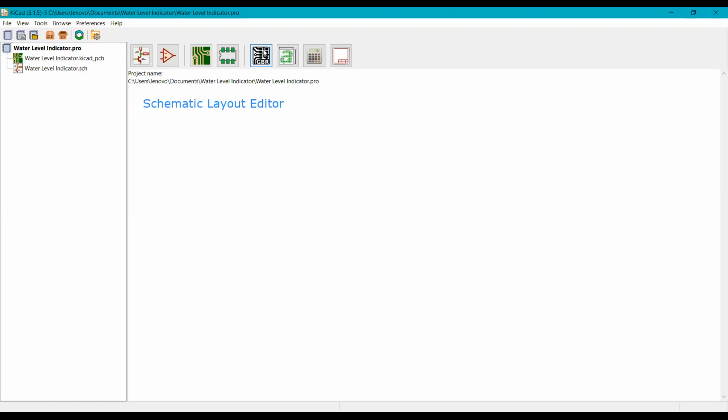Then you will have to generate your Gerber file, and there is one more file named CPL, which is the parts placement file, where it will tell you at what exact location your components are placed on the PCB. So this is the Gerber file which you will send to the vendor or the manufacturer who will make your PCB. And this is the PCB calculator.